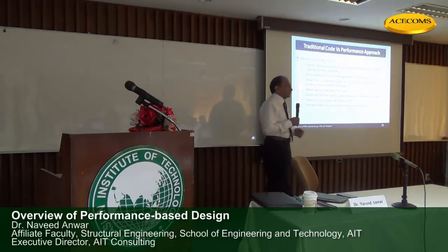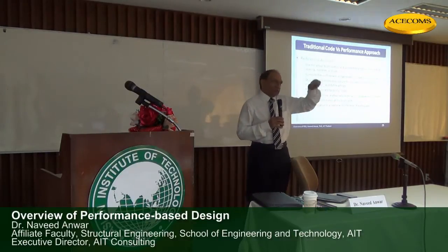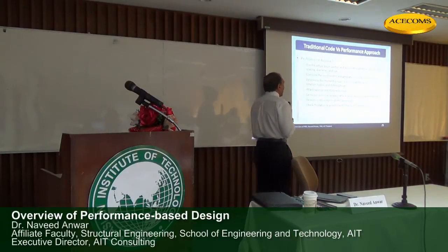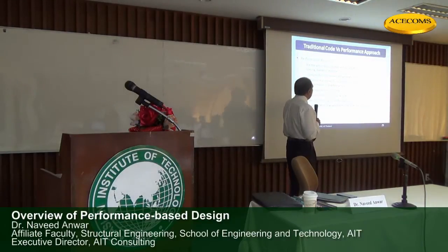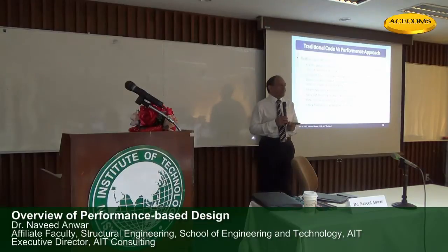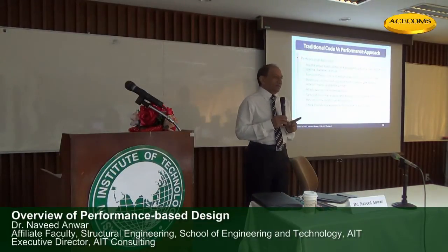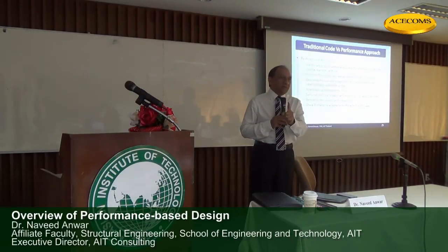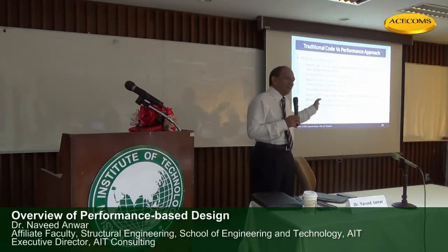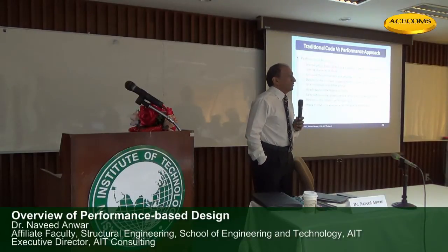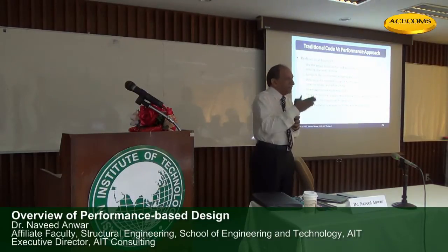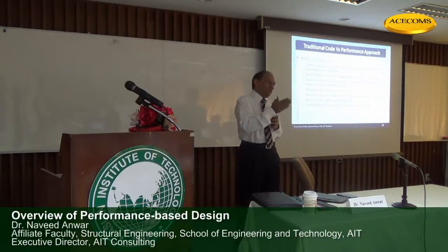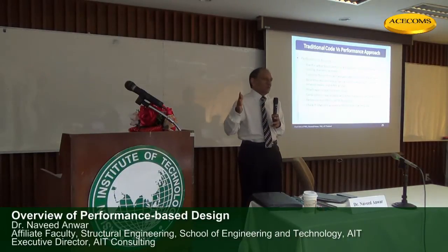Attach an appropriate hysteretic model for the cyclic damage. Carry out nonlinear analysis where demand and capacity are linked. Determine the rotation at that beam and check if the rotation now is okay or not. So 100 millimeter, 125 millimeter, 150 millimeter, 200 millimeter, they might give slightly different results. You will find later, I will show you a slide, hardly much difference in the confinement or the moment curvature or moment rotation capacity provided by 100, 125, 150 and 200. But the codes would have us believe that if you go 1 millimeter above 100, oh, something's going to happen.